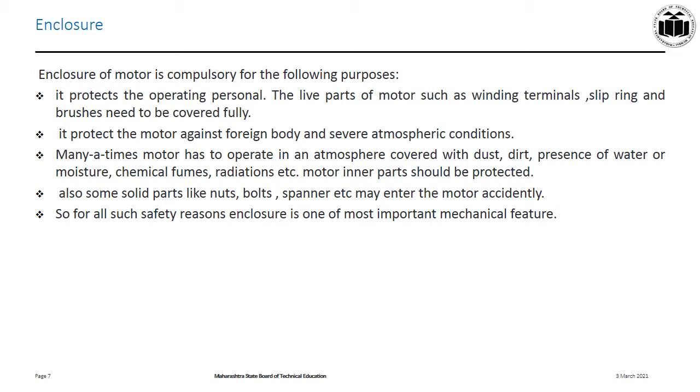Enclosure means cover. So enclosure of motor is compulsory for the following reasons. First of all, it protects the operating personnel from the rotating parts. Also, the live parts of the motor such as winding terminals, slip ring and the brushes need to be covered fully.